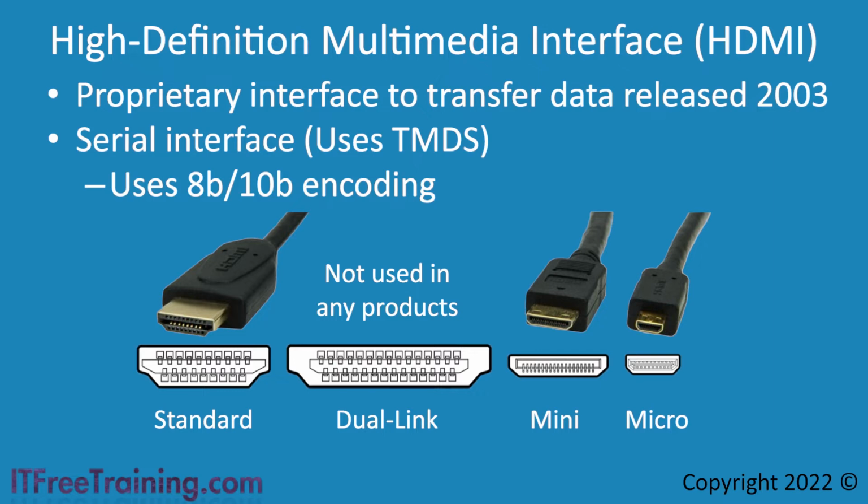Essentially, clock skew is when the data lines get out of sync with each other. Having these extra bits allows HDMI to work out if clock skew has occurred and correct it. This becomes important when the transmission rate increases. It also helps HDMI to run longer cables and helps make them cheaper to manufacture.